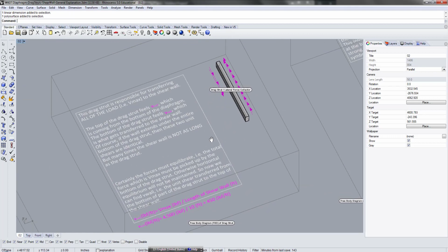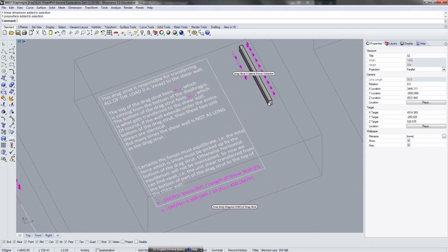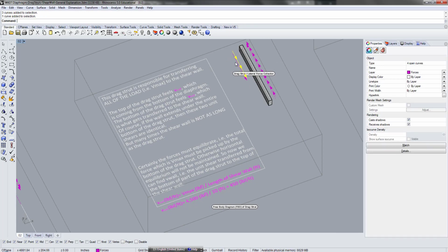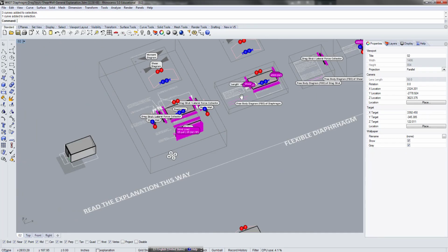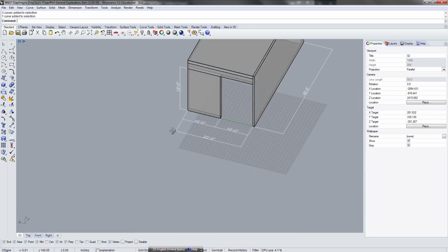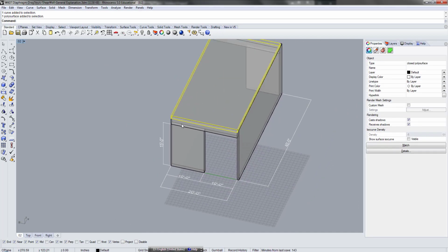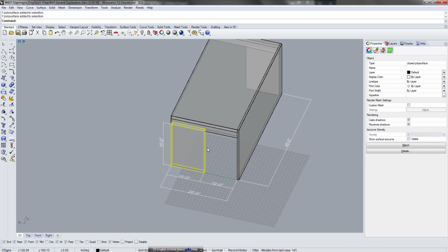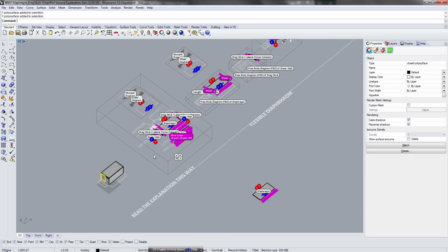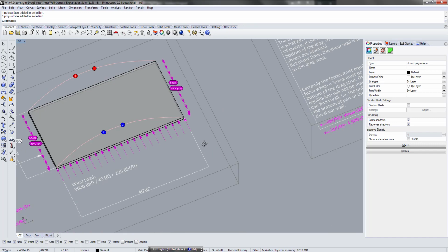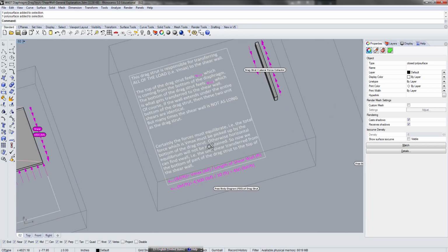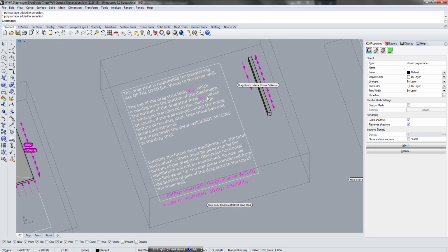You can also calculate the linear shear for the wall side. If you go back to the original diagram, you can see how the diaphragm was 20 feet long and the wall is 10 feet long. So the length is actually half. Sorry for moving around too much.